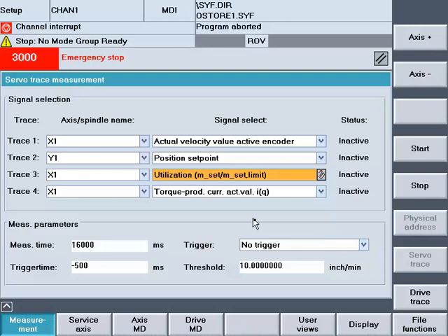The reason we're not looking at total current is that there are other things that can draw current besides just the torque producing part. For example, with an induction motor, you're going to draw some current just to induce the magnetic field in the induction motor and make it spin. That's not generating torque, but it's still total current, which is why we don't look at it as much as torque producing current. Same thing, certain permanent magnet motors run at higher speeds will also have some current that they use to be able to run above rated frequencies or rated speeds. So in general, without having to do all the thinking, we just look at torque producing current by itself.